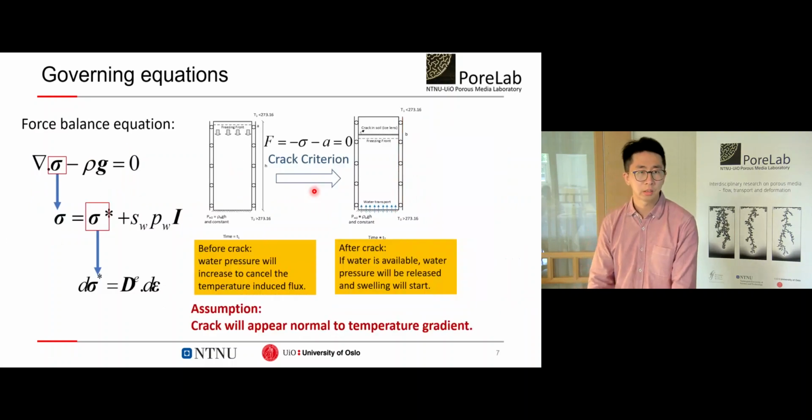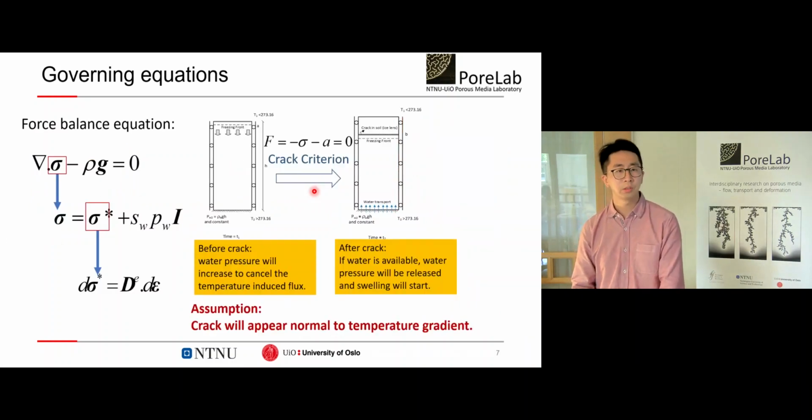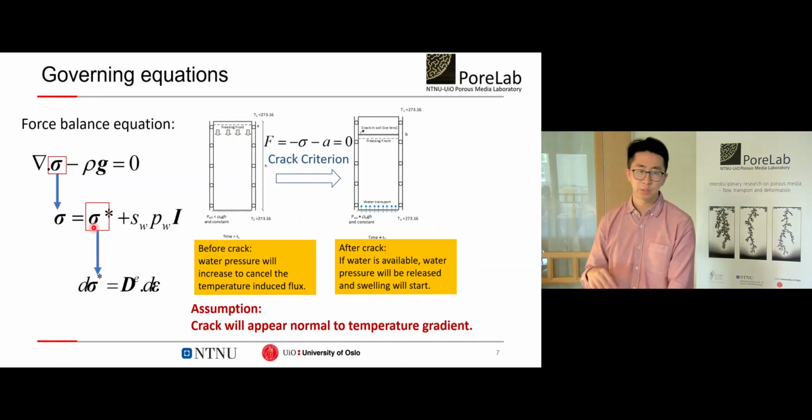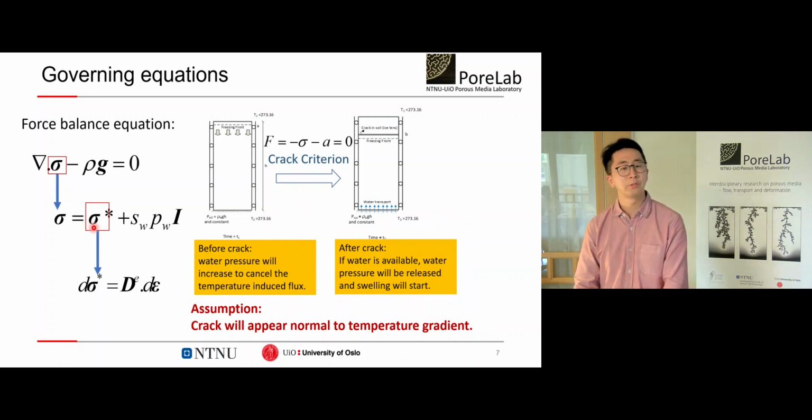And the last governing equation is the force balance equation. And here is the total stress, which can be decomposed into the normalized water pressure and the solid phase stress. And this solid phase stress is a combined stress of soil grains and ice. And it's also the part of the total stress responsible for mechanical deformation. So we need a constitutive model here.